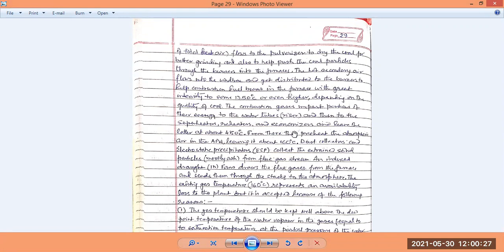Okay. Next, that heated air from the economizer goes back to the preheater. Again, it is preheated, preheating the incoming air, and then generally leaving it at a temperature of 160 degrees centigrade. So the temperature at the furnace starts from 1350 or 1400 degrees centigrade.